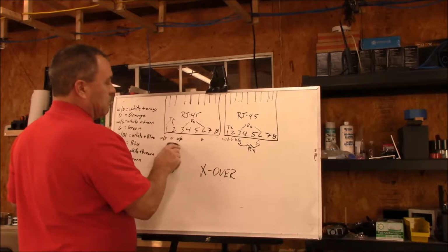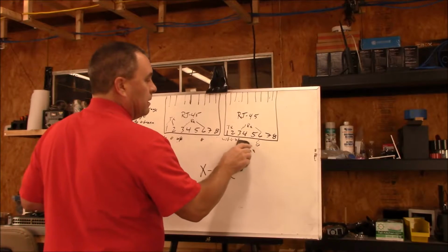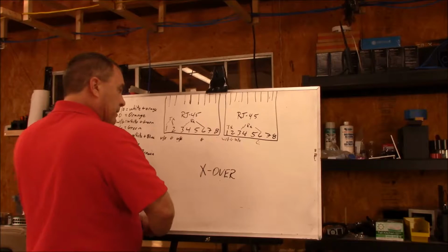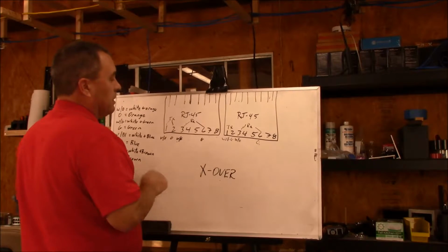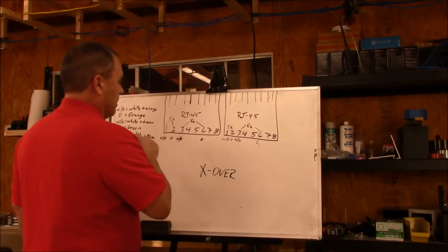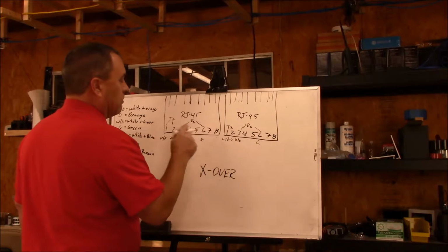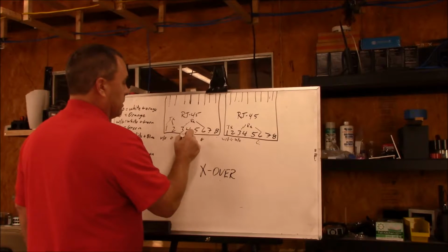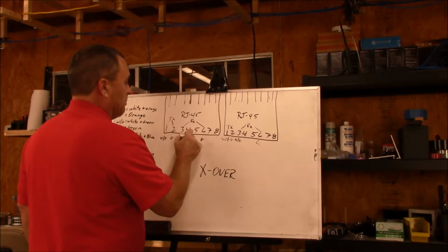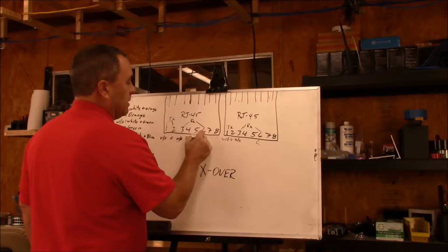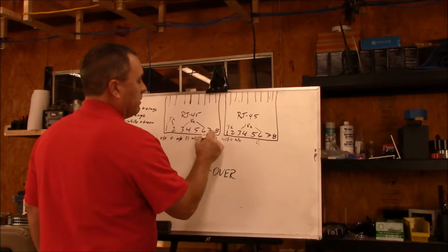So, okay, we've started building our cable. We've basically crossed it over. Now we just need to add the rest of them, and the rest of them are going to be mapped exactly like the straight through. These don't roll over or cross over at all, they just go. So now you've got blue, and then white blue, and then brown.